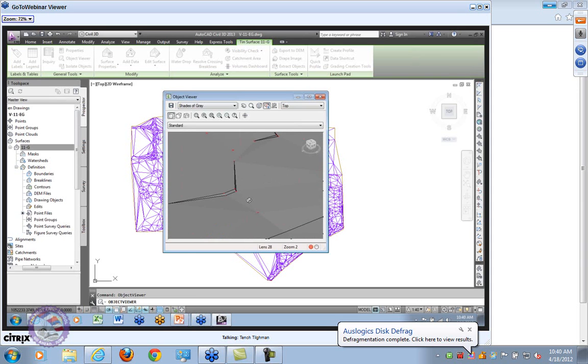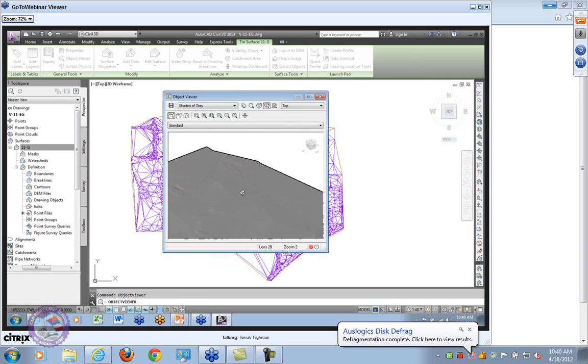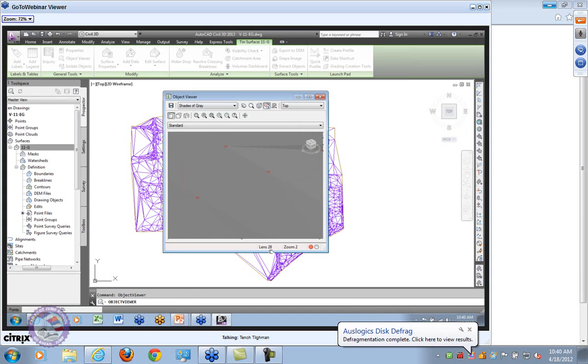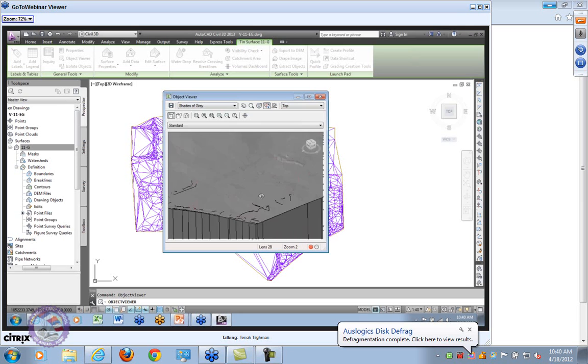And remember, this is pure point data. I have no features, okay? No figures, no break lines, no faults. Pure point data, proximity based, and I haven't massaged it in any way, shape, or form. Also, my style shows me where my data points are, and I've got this big huge area with no points at all. What the hell is going on there?